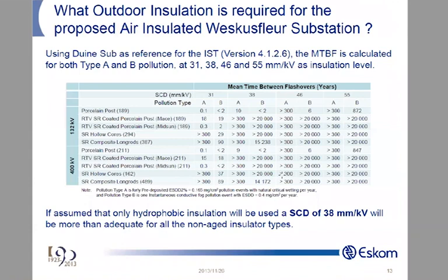Now, mostly on silicone, you don't get tracking, because tracking is a conductive path. So if you want to determine whether it's tracking or erosion, you would take a megger with 2 pins, and then you put it over the area, about a few centimeters in between, and then you measure.